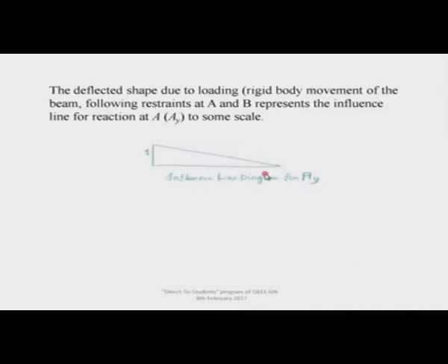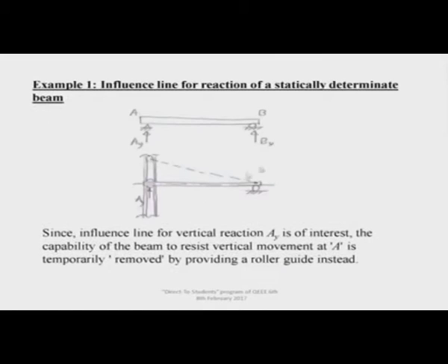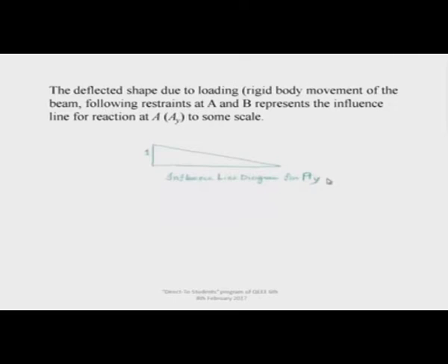So, this is the influence line for, actually, it is Ay. The y direction is this, and A is this left point. So, it is Ay basically, it is not Ry. Now, if I put 1 here as normalization, then all the ratios are actually maintained accurately.